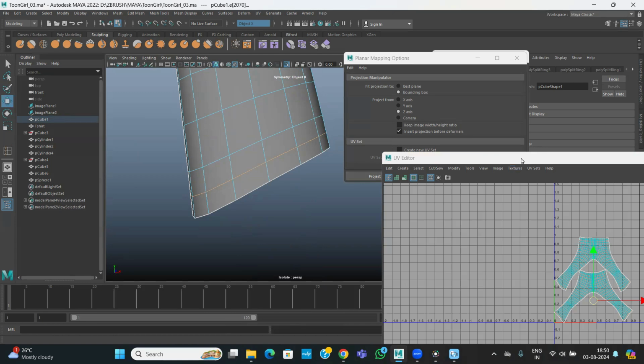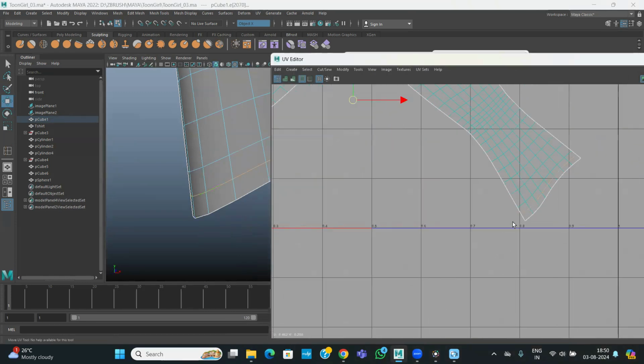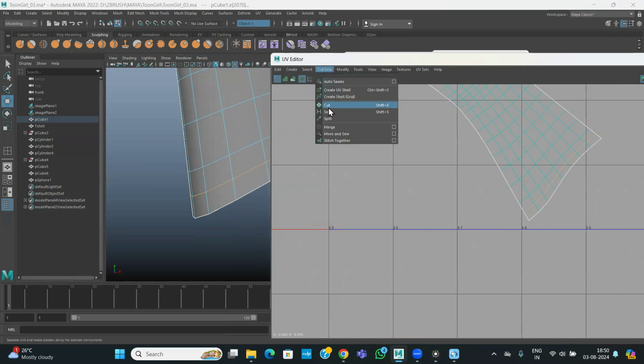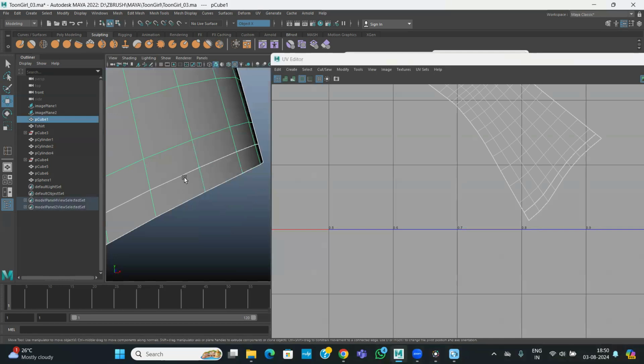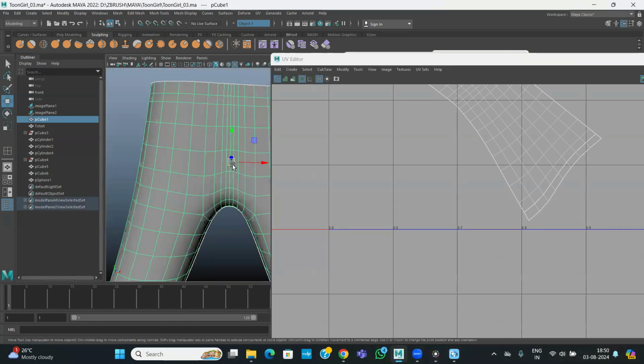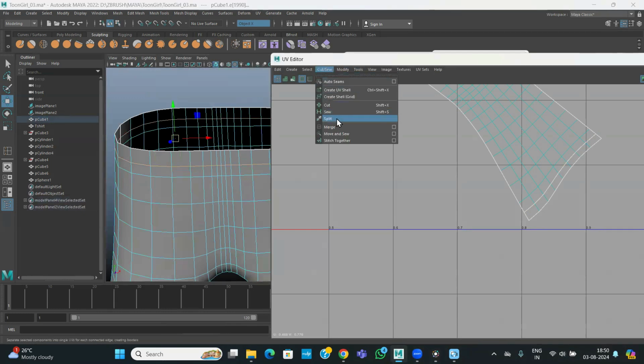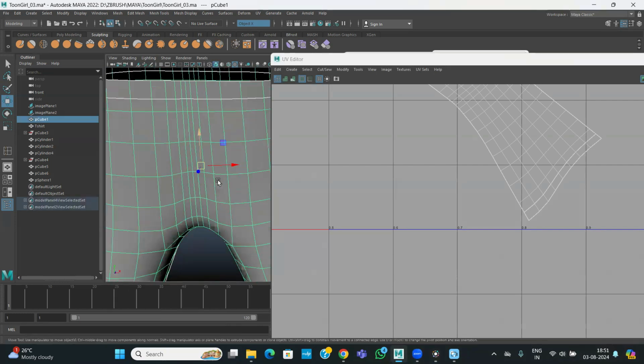So how to make that? As I explained in the last video, same thing. Just you select, already selection is there, and use the tool called cut. So immediately you can see you got some white color thick line, that is called seam. So that area you can have stitching, and of course in this area you want to have stitching, and you have to have here also. Okay, so wherever you want, just you cut it, and you get the same point. And here,